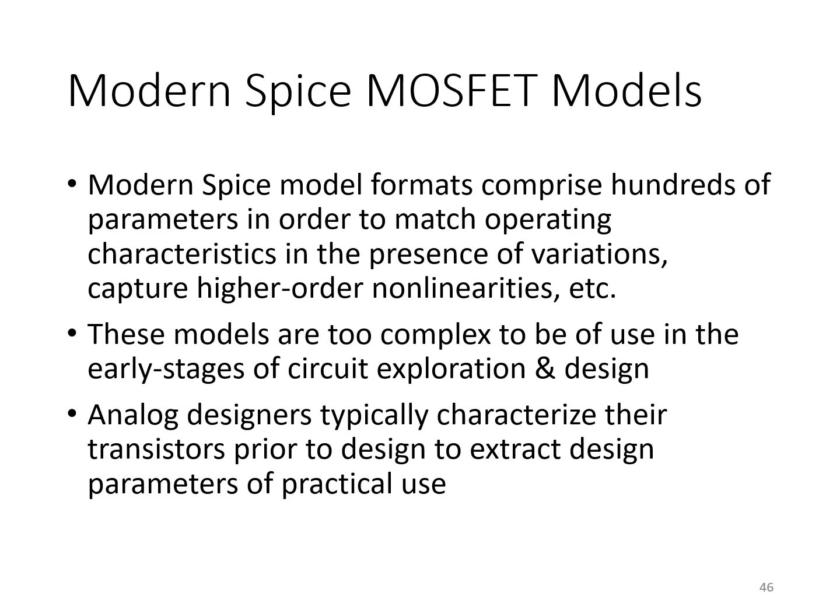Again, the motivation here is that modern SPICE model formats often have hundreds of parameters in order to match all the operating characteristics of the transistor in the presence of variations, to capture high order nonlinearities, temperature effects, sizing effects, proximity effects. And models like that are just too complex to be of use in the early stages of circuit exploration and design. We need to go through this process of extracting a simpler first, second order model of the transistor parameters to allow us to draw some intuition from these complex channel models.